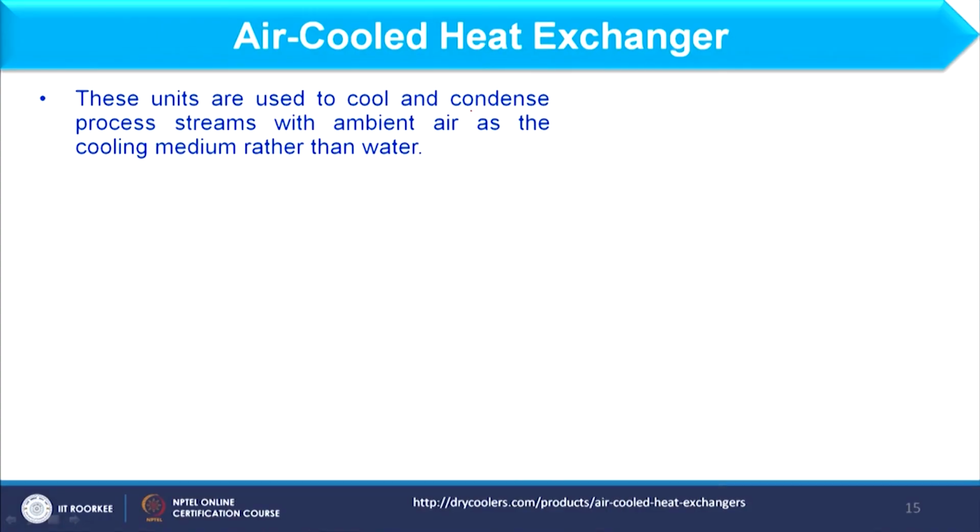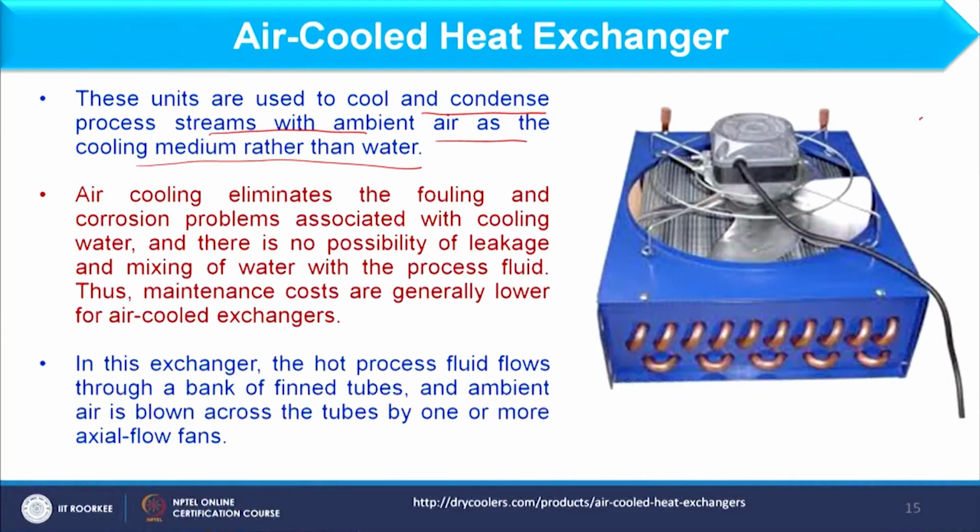Air cooled heat exchangers are used to cool and condense a process stream with ambient air as the cooling media rather than water. Usually for condensation purposes we use water, but here we are using air as a cooling media, and the second fluid will definitely be the vapor which is to be condensed. If you see this schematic, when the fluid is to be condensed, that fluid should flow inside these copper tubes.